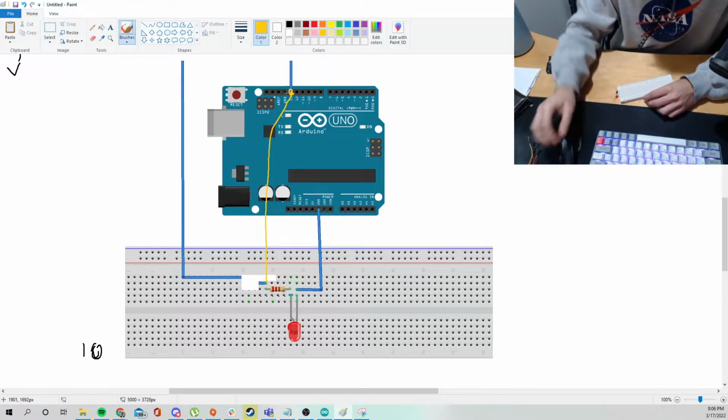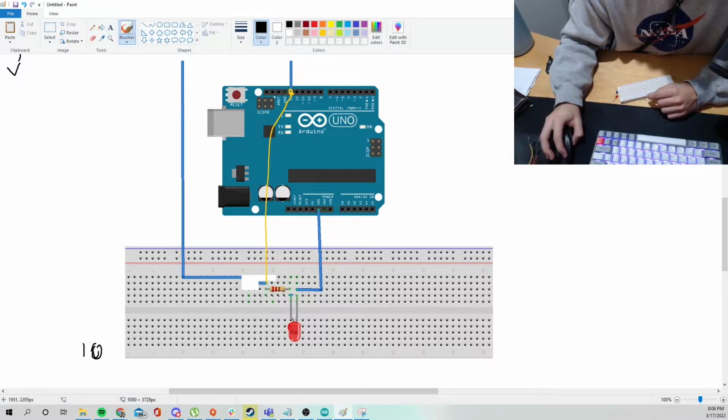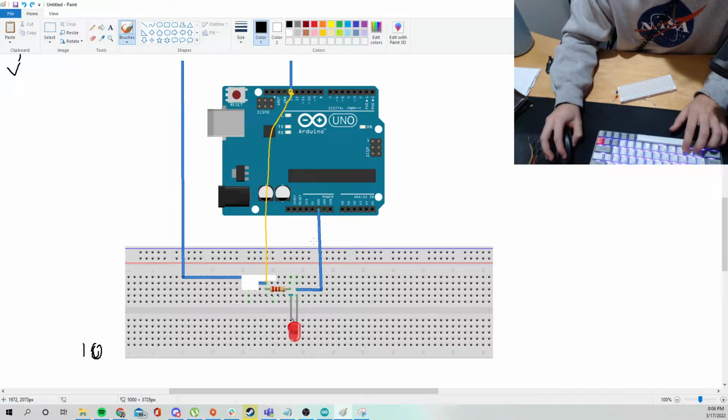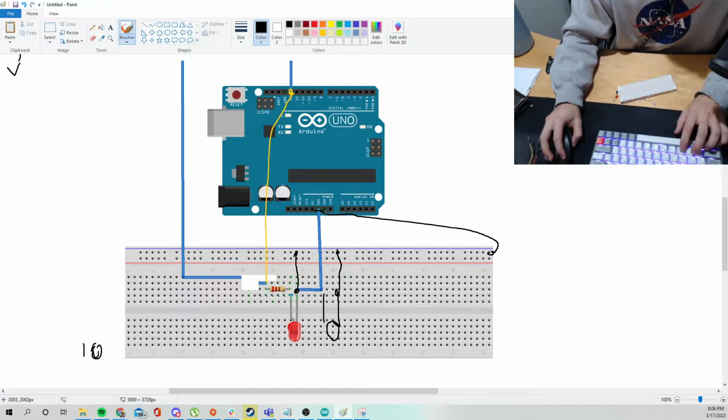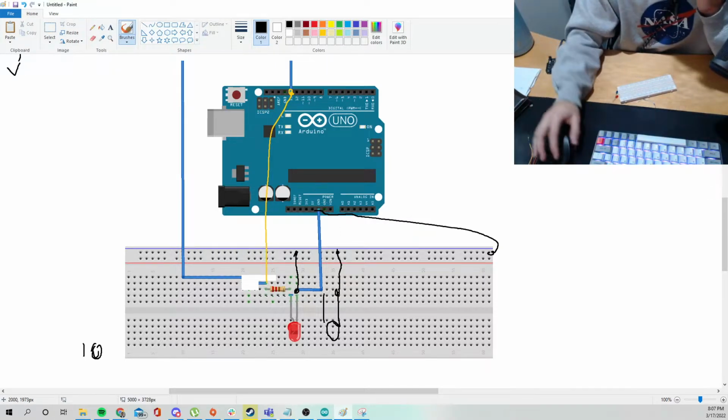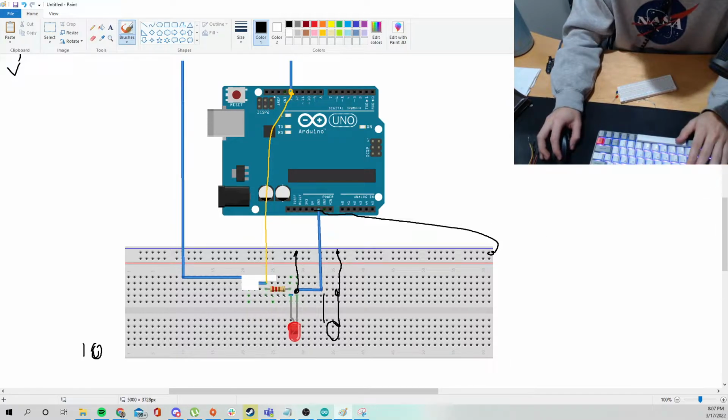Now, something you'll notice is that it needs to be grounded like everything else. So this here, you can see it right here, it's grounded, and instead of grounding it separately, because I only have 2 ground pins and I don't want to use them all, what I'm going to do is connect this to my ground rail at the other LED here, let's say, and connect this to the ground rail as well, and then later on I'm going to connect the ground rail to my GND, to my ground pin, and that's gonna ground everything. I don't need to actually do it separately.